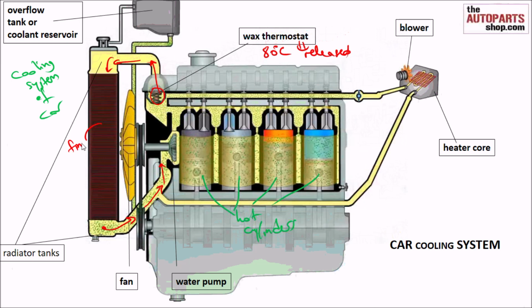So you have the fins to help the heat exchange, and you have the fan here. And as we have said, if the fins are not enough, the temperature increases to higher values, for example 90 degrees Celsius. When the temperature is 90 degrees Celsius, the fan starts, okay, because the cooling by the fins is not enough, okay.